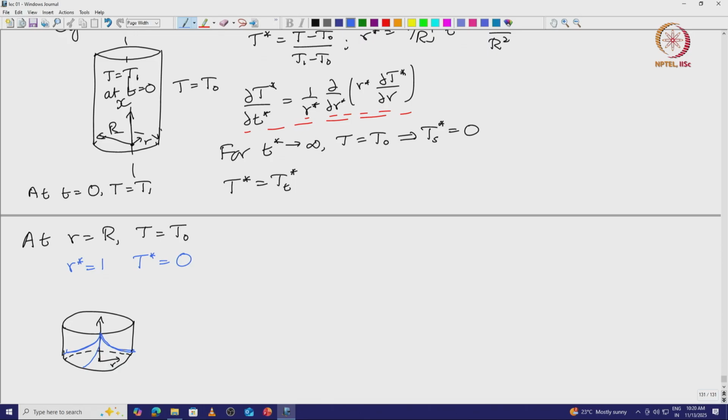This axisymmetric condition implies that if the slope is non-zero at this point, that means that the slope is not uniquely defined, because when you approach from different directions, the gradient is different. The gradient is along the radial direction. As you vary the angle around the axis, the gradient is in different directions.